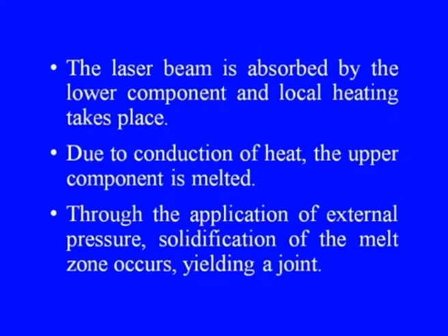The laser beam is absorbed by the lower component and local heating takes place. Due to conduction of heat, the upper component is melted. Through the application of external pressure, solidification of the melt zone occurs, yielding a joint.